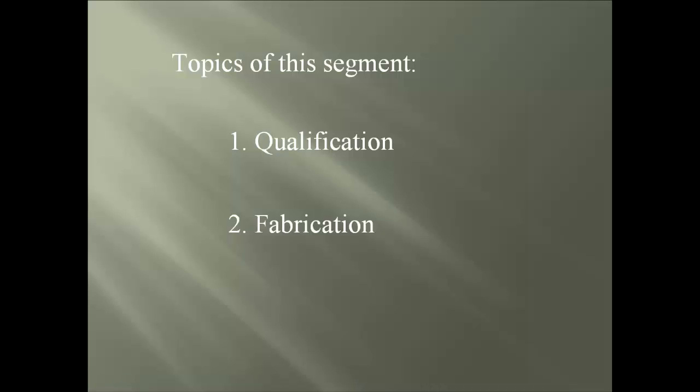Second topic is the fabrication, which defines the ability of welding sheet metal like such items as steel decking, panels, storage racks, and stud or joist framing members, while enforcing the proper techniques and code compliance requirements so to produce sound weld joints. Last topic is the observation. Although the code is vital in guiding the assembly of the weld joint, there is still the need for observation during the production phase. By this performance, it will verify the quality of the weld has been performed as per the code specifications.